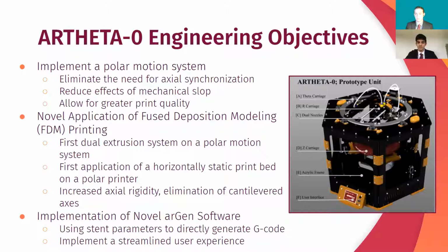We were able to solve this, however, by implementing the polar motion system, which requires no axial synchronization for circular geometries and only the actuation of the theta axis. And it minimizes the effects of mechanical slop. All of this combined allows for greater print quality.